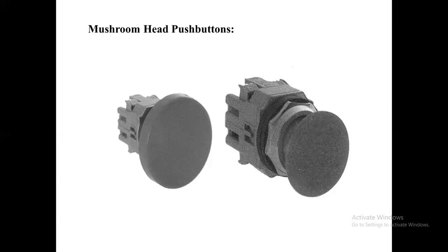However, since it is not recessed, the level of protection is not to the extent of the guarded push button. This type of switch actuator works better in applications where it is desired to back-light the actuator, and these are called lighted push buttons.